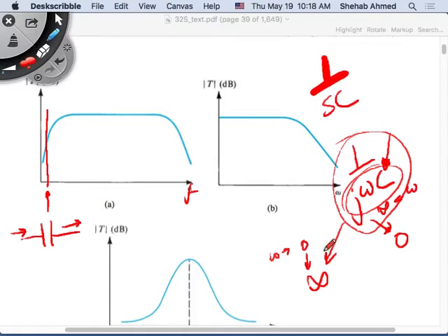So at 0, fine, it's like an open circuit still. But at 0.1, C is huge, C is infinite. If C is infinite already, then the impedance will be 0 automatically. How does it affect this curve? It will make this fly up here, right? Very quickly, so that I will not be attenuating low frequency signals. So this requires large capacitors, right?